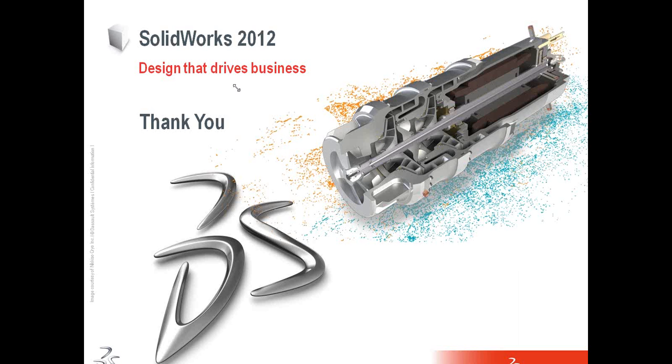For those of you who are interested, can stay back. The first question is, can we align dimensions with magnetic lines? In SolidWorks, we already have a snap feature which will align dimensions. So if you want to align one dimension with the other, SolidWorks already has something called a snap feature. These are small yellow snap lines that will help you in placing the dimensions.